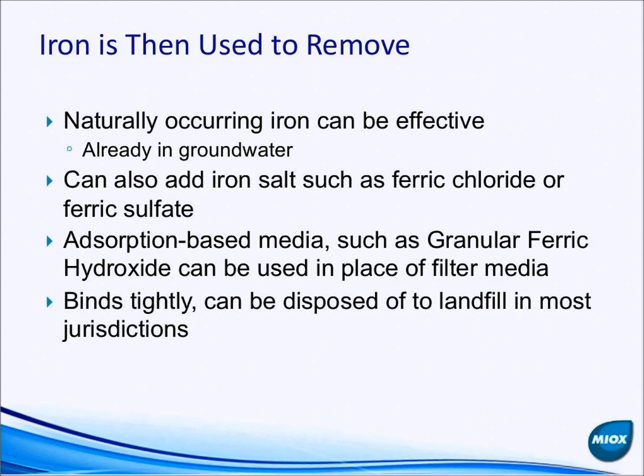One thing that's very nice about it is that it does bind very tightly to the iron, and in most cases that can be disposed of to landfill. There are probably a few jurisdictions that don't like you to do that, but by and large, most of those iron-bearing medias or your backwashed iron is just landfilled, or just run out to a red water filter or something like that to get rid of that iron and the arsenic.